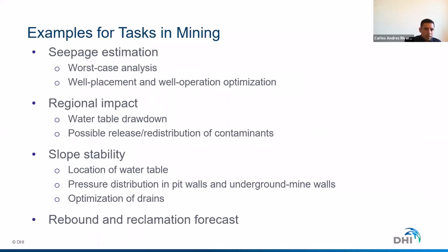Just to mention a few of the examples that are involved in mining applications. The most common is dewatering estimation. We want to estimate what is the dewatering volume that we need to pump out of the system. So here comes the question: I can bring this into a model, I have one picture, but I can also extend this situation and define what is my worst case scenario. Maybe comes a flooding event, so I have higher rises of groundwater levels. I would like to be in the position as a modeler to understand all these worst case scenarios. FEFLOW can give you these options, now in combination with our automatic calibration tool, FEPEST.